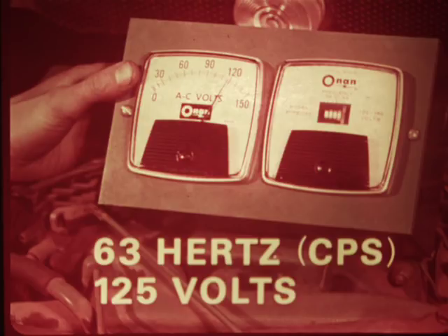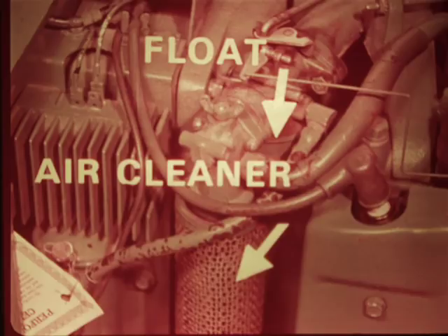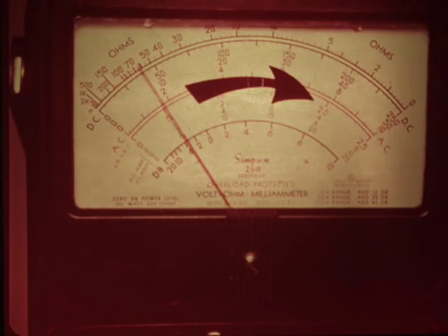To tune the engine, check the no-load output first. Then service the air cleaner element and check the carburetor float valve and float. Check the ignition system and set the timing to 25 degrees before top dead center. To test the compounding reactor, measure the field voltage in load and no-load conditions. If a load doesn't boost reactor output to the field, the reactor must be replaced.